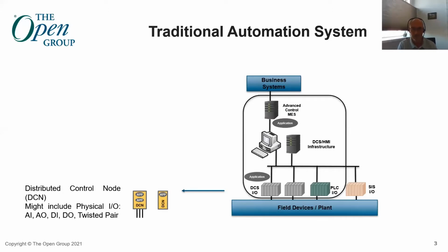As you can understand, the DCN is everything we can do with level 1 today. So it will contain I/O as well as some sort of compute power to run programs, our base layer control, if you will. But it can do more than just that. You can see that there is a DCN with no lines on the south side, on the bottom side, which means that it's just an edge type of device containing an app, which would mean that there is some smart application running in the lowest bottom side of your system, if you will.